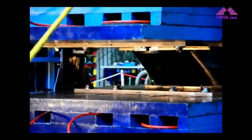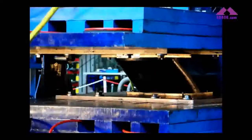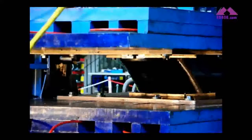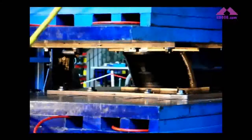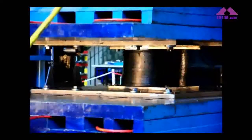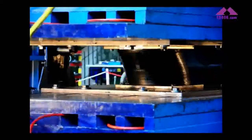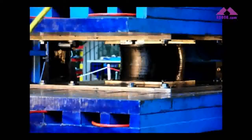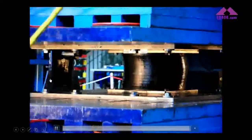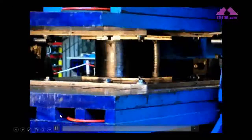1,000 tons of pressure on top of the isolator, and the isolator will make a maximum displacement of 375 millimeters, nearly 40 centimeters. This is a small scale isolator. 10,000 kilonewtons compressive force on it means that, taking an average car today as nearly 1 ton, maybe 1.5 tons, there are 1,000 cars on this isolator, and it displaces up to 40 centimeters.